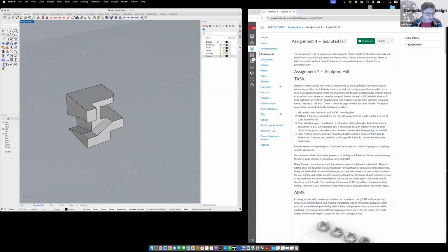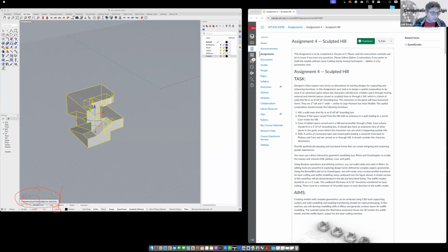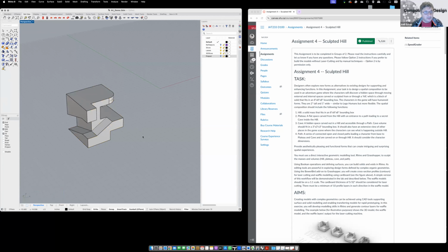One is I'm using inch as my drawing unit when I'm building it. It's inch. And also when I select my model, it gives me this message. It says it's a closed polysurface, right? It's like a solid. So if you see these two things, okay, you are ready to go to the next stage, which is we will create a sub-D version of this.